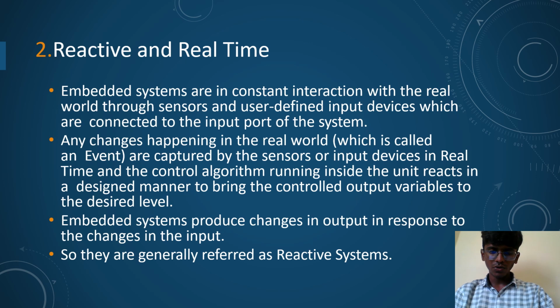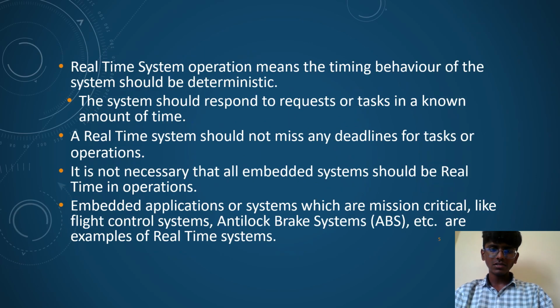Embedded systems produce changes in output in response to changes in the input, so they are generally referred to as reactive systems. In a real-time system, the timing behavior of the system should be deterministic. The system should respond to a request or task in a known amount of time. A real-time system should not miss any deadlines for task operations.